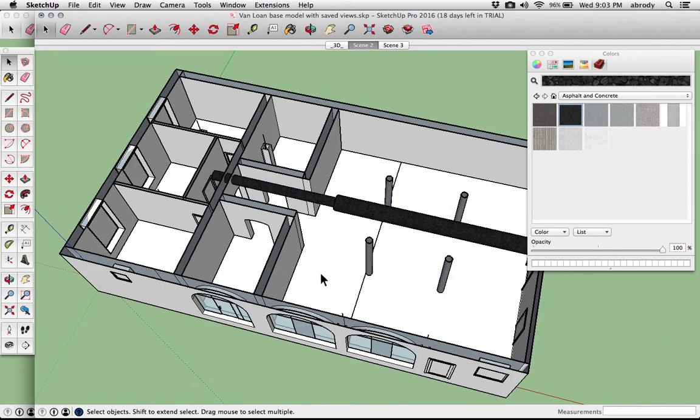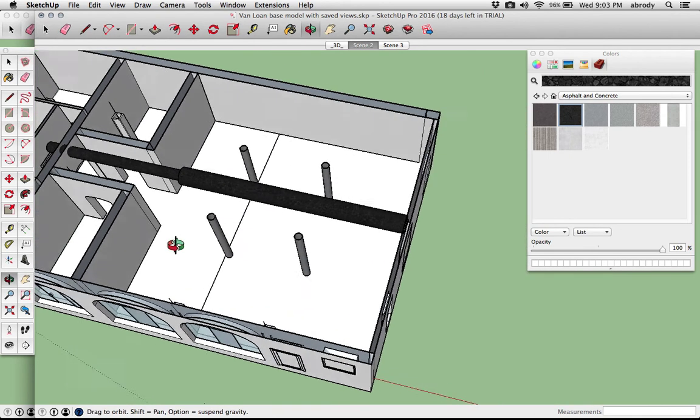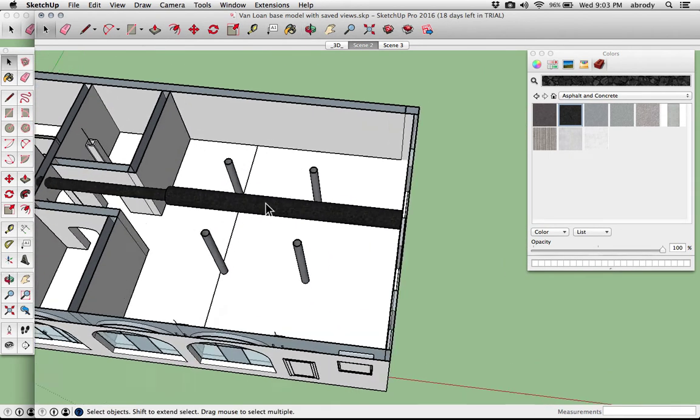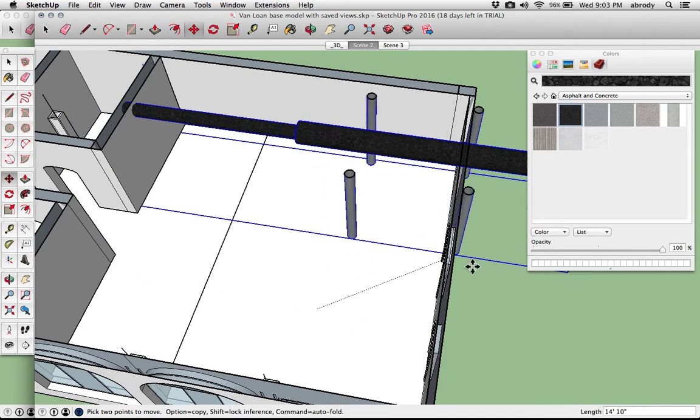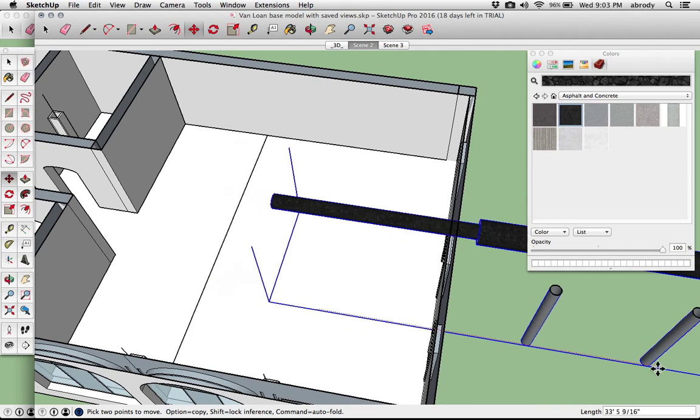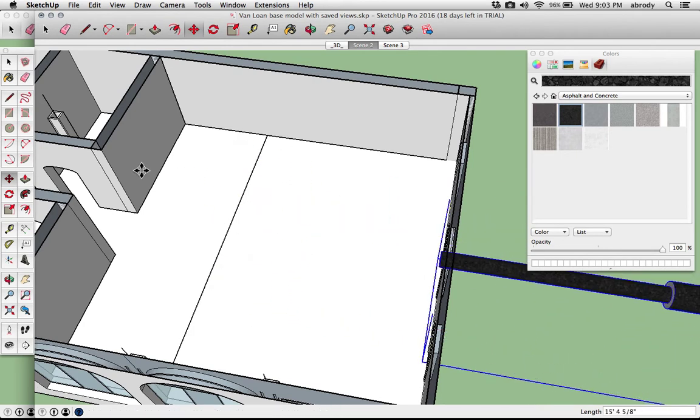All right, a few other things that you guys are probably going to want to do are things like walls. To do a wall, I'm just going to delete this component or move it out of the way for right now, so that we have a little bit of space. And to draw a basic wall is very easy. The simplest thing, and again, this is a sketchy program, so you don't need to be too precise, you can basically just draw a rectangle. Now, as I'm drawing, notice down here the dimensions, 20 feet, 1 3/4 inches by 1 foot 6.